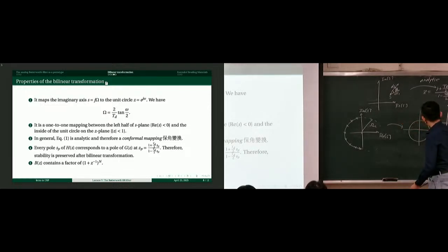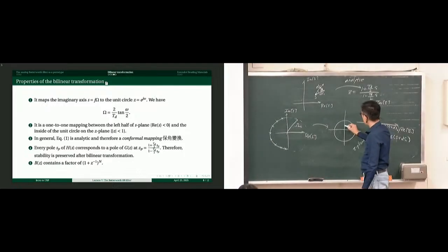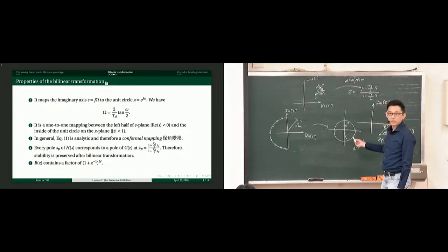Okay, so now from S to Z, this is the Z plane. Now these poles, wherever they are, are going to be inside the unit circle, might be something like that. We have equally many poles now in the Z domain, but all of them are guaranteed to be inside the unit circle. And isn't that great? Make the response great again, right? Because if all the poles are still inside the unit circle in the Z domain, we know that this corresponds to a stable and causal system.